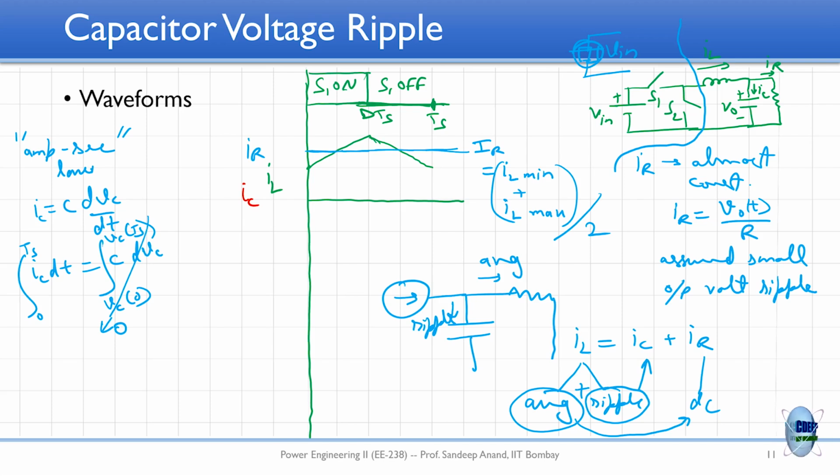In the same figure. Why don't you guys go ahead, draw it in your notebook. Draw IC in the same figure. How would IC look like? Let's start from somewhere. Go ahead. How would IC look like? Just explain, I'll draw it. It will be a triangle but below. So IC is nothing but Kirchhoff's current law, IL minus IR. So just apply Kirchhoff's current law at each instant.